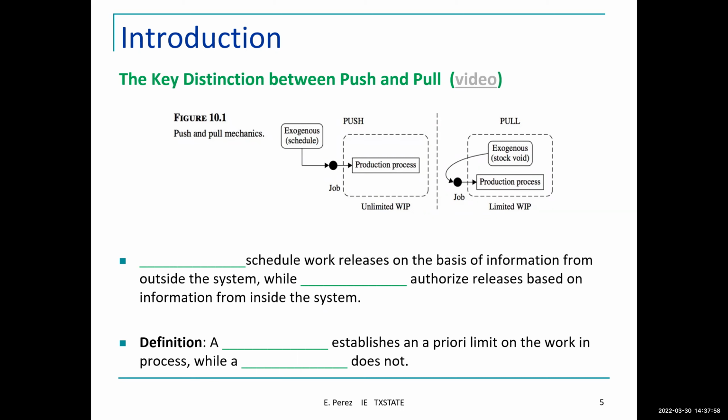So let's say you're producing 10,000 parts. If you're waiting for those parts to be completed in order to move them to the next process, then the amount of WIP that is staying in the system is high. 10,000 parts at the first station. Will every part go from station 1 to station 2 only after the whole 10,000 are done? Or will station 1 work through every part and then it goes to station 2, or will it go one by one?